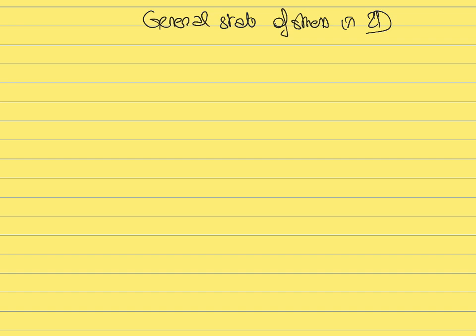If the surface is very small, then this force is going to be applied to a small surface, and in that sense you will have a high stress, you will have a higher risk of fracture. And if the surface is very large, then the force is going to be distributed over a large surface, and in that case the stress will be lower, and the risk of fracture will also be lower.